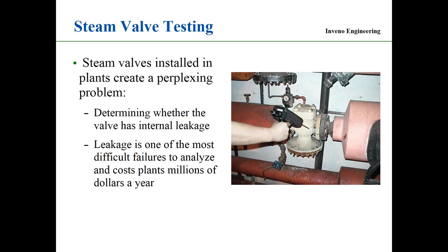Valves leaking through create issues with pressure reduction stations, overpressurization, safety valve relieving, and steam valves leaking through on process applications. Then we get heating going down into the coil systems, heat transfer where we don't want that to occur. So it comes down to: how do we test valves for internal leakage?